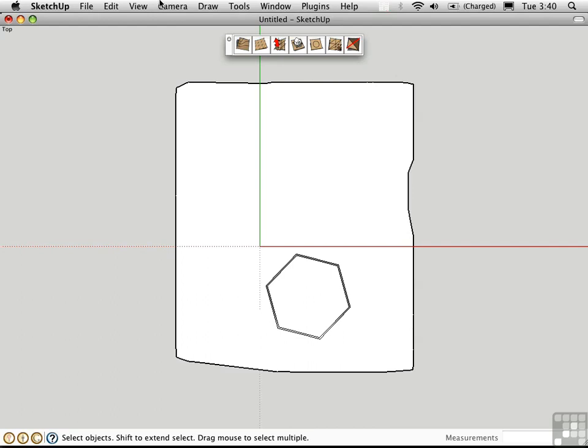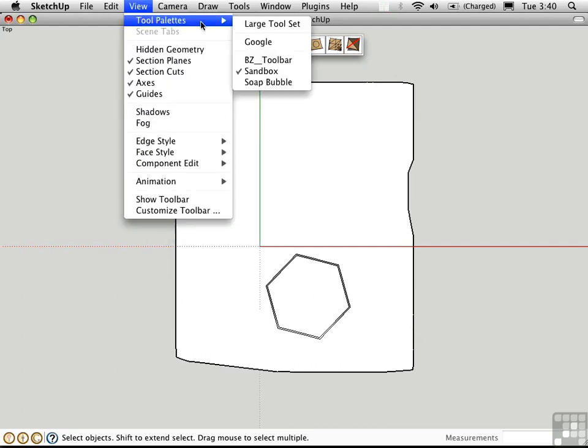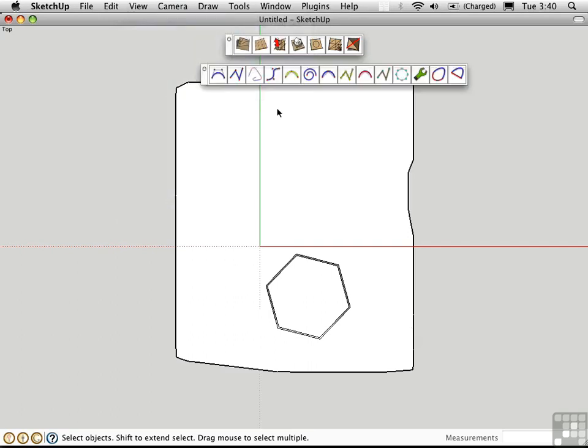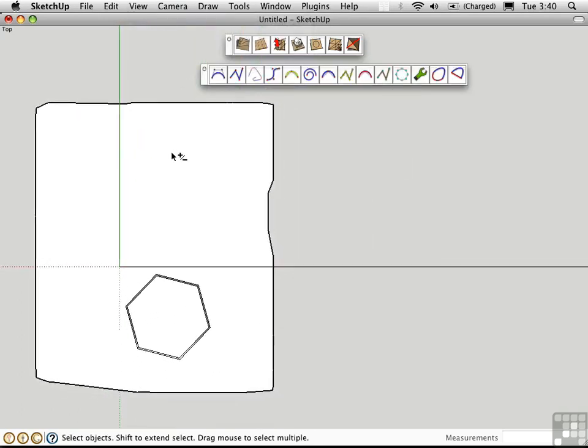I'd like to create a curved path, so I'm going to use the Bezier Spline toolbox for that. I'll just go over here. Now I'll use a classic Bezier curve. And I want to be careful that I don't actually snap it to the landscape itself, thereby making a three-dimensional curve. Instead, I want to be sure that I have a two-dimensional curve so that I can make a face.